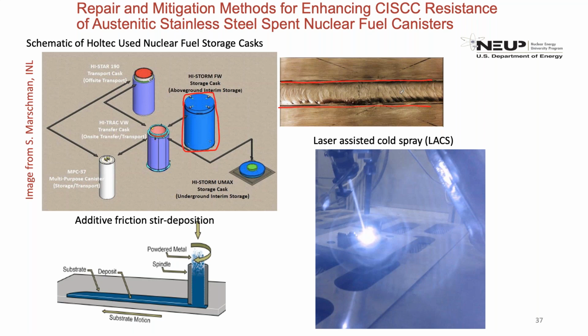And you may know that you can get large tensile residual stresses in the heat affected zones of austenitic stainless steel welds. It's also possible to get sensitization in those areas, and that combined with the salt mist atmosphere can lead to intergranular stress corrosion cracking, which is not good. And so there's a large effort with many institutions trying to figure out how to repair these welds in situ, right? Or at least do preventative maintenance or both.